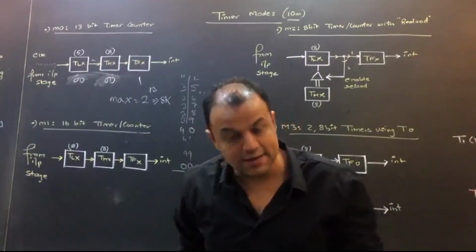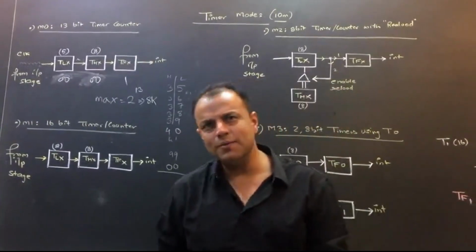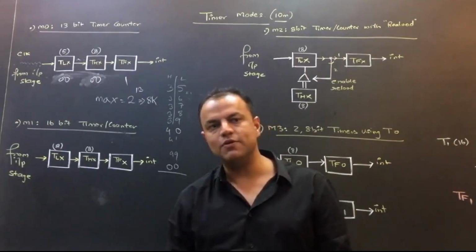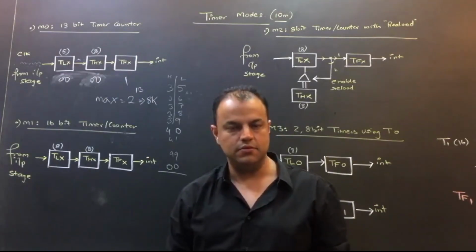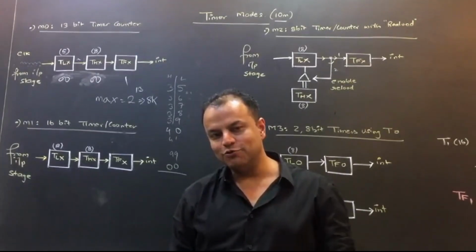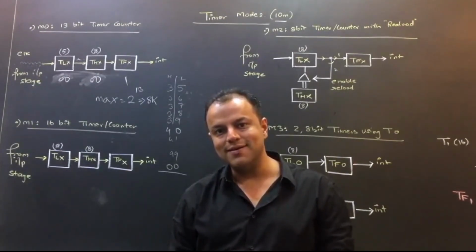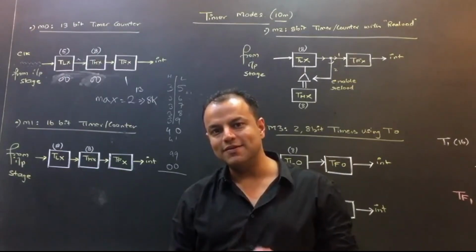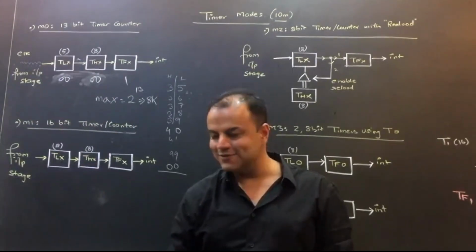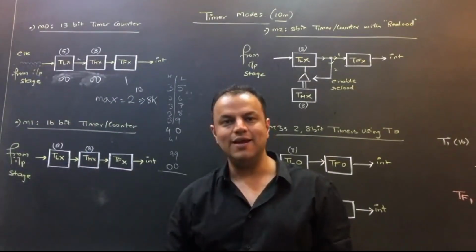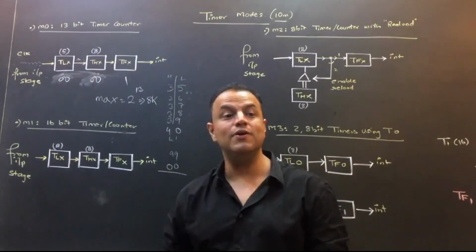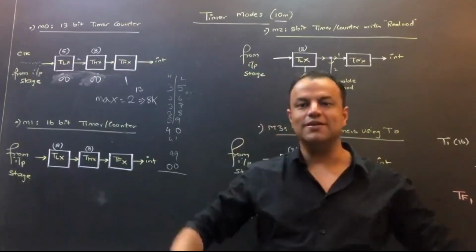Now when you do serial communication, that's going to be a next video after we do timer programs. You'll come to know. In serial communication, the baud rate formula is 2 raised to SMOD upon 32 into timer 1 overflow rate. No, relax. I have not even taught you that formula. All I'm trying to say is, if you pay attention, what is the formula? 2 raised to SMOD upon 32 divided by 32. That means, can you see there is a division by 32? And this is a mode to divide a frequency by 32. You think it's a coincidence? No. This mode is used to create an artificial serial port where you can divide a frequency by 32 and get the same baud rate which the actual serial port does.